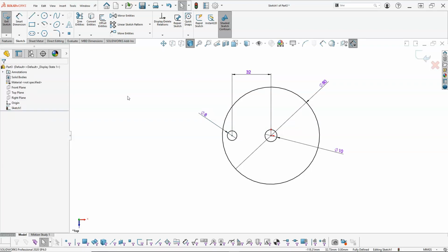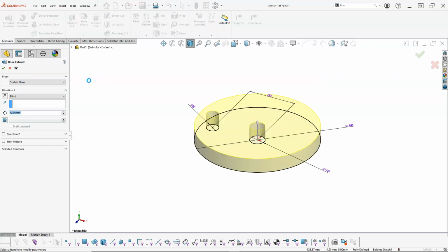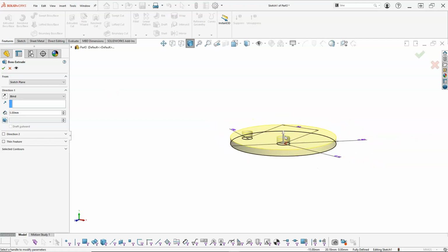Go on. All right, so this is going to extrude to a thickness of 5 millimeters. So Features, Extrude, blind end condition, enter the value. As long as that's highlighted in blue, I can just start typing and it's going to overwrite. Tab will update. And then I have to decide how I want to build this.